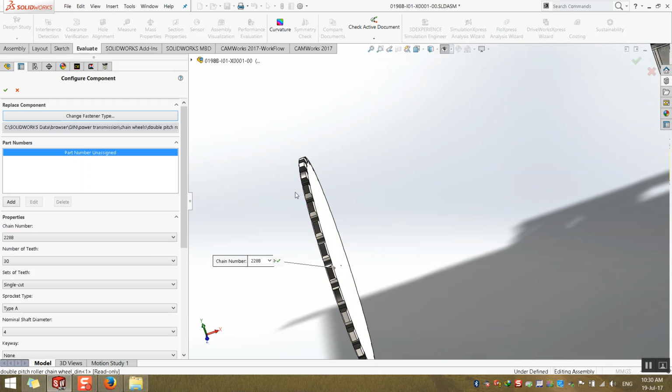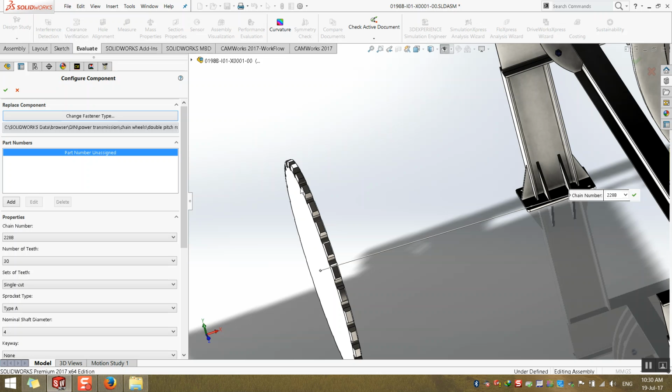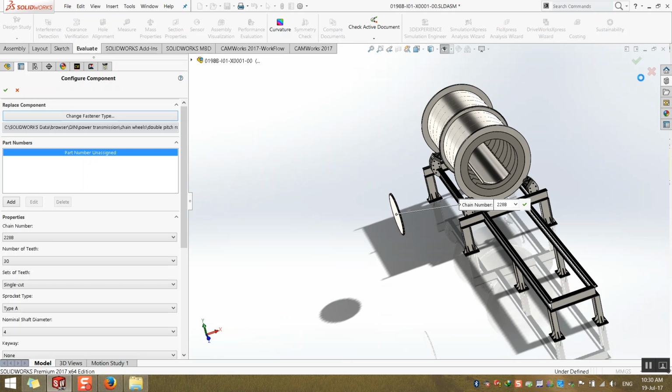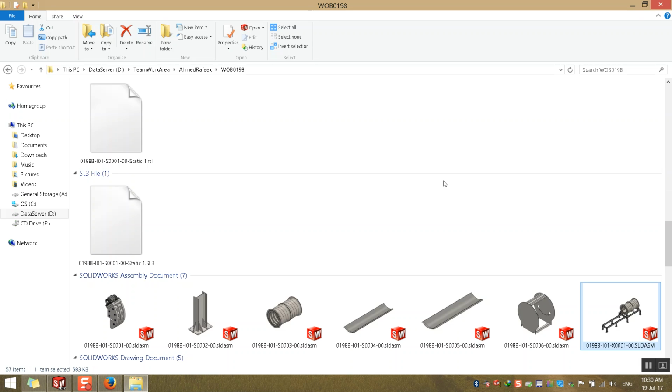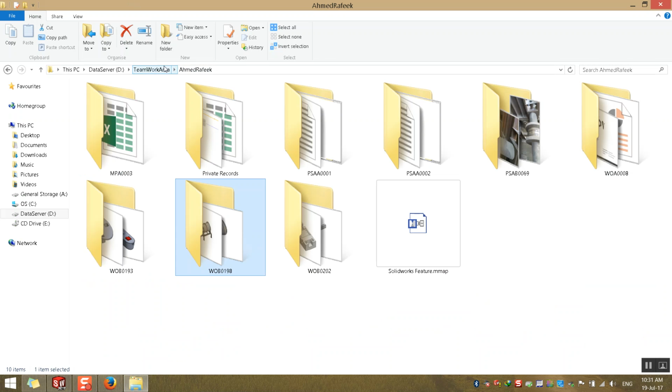You can get structure analysis. How do you test your model, stability wise, in SAP, or can you do it internally? Yes, you can do load calculation internally in SolidWorks. SolidWorks has bought Cosmos. You know Cosmos? SolidWorks bought the Cosmos company, Cosmos Solution, and uses it now as internal SolidWorks Simulation. They use American standard or your standards, according to your British standard. Yes, British standard. So you can do load calculation.